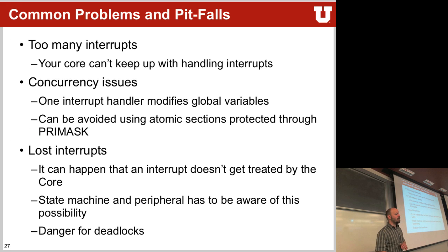Okay, a couple of very common pitfalls that can happen. If you generate way too many interrupts, you can overrun your code, and you will just always be stuck in an interrupt handler, and you will never execute your main code anymore. If you just keep generating the same interrupt way too fast, and your interrupt handler didn't have time to execute an exit, it will just tail chain the next one and the next one and the next one. You're stuck in your interrupt handler.